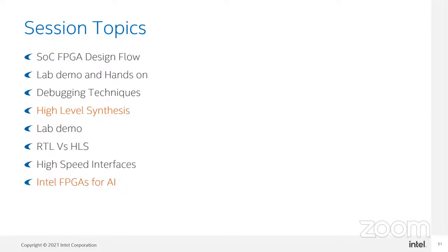The basic objective of today's discussion is that we are going to use the concept called high-level synthesis, in which we are going to use the tool called the Intel HLS compiler, which is a high-level synthesis compiler. We are going to convert the C or C++ code into an RTL. After converting the C++ code into an RTL, we are going to analyze what happens when the code gets converted into RTL and what the different methods of optimizing it are.